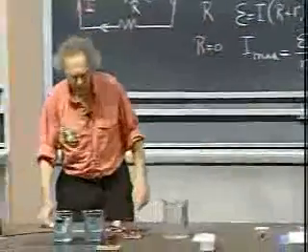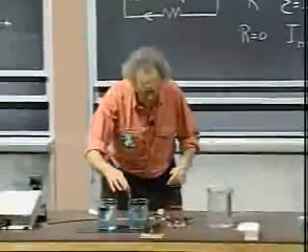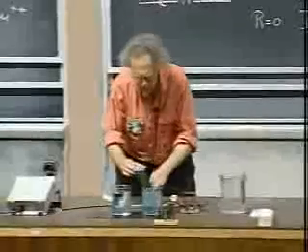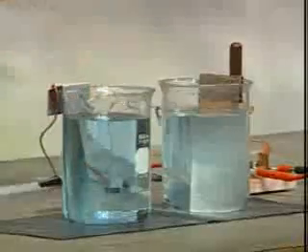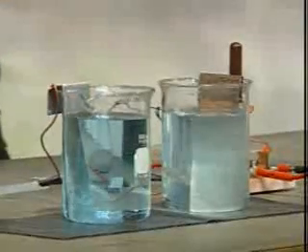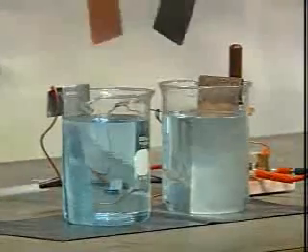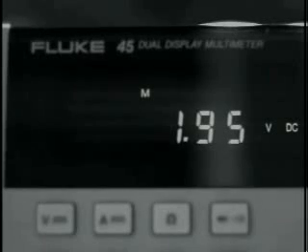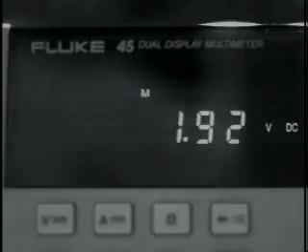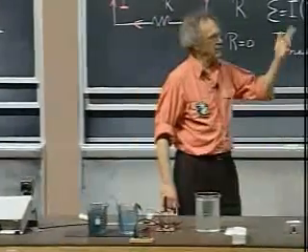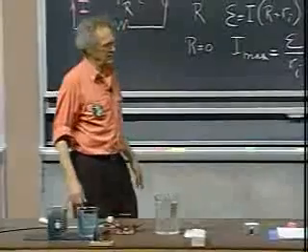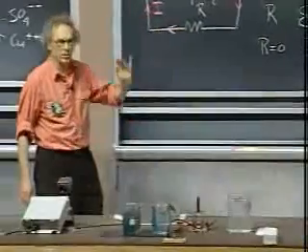So if we're ready for that, this is my second one, is going to be completely independent. So here comes the other 2 plates. Make sure that I have the copper and the zinc not confused. There we go. And now you should see twice the potential, and you do see that. It's open circuit, there is no current running. Well, there is a minute little small current running through the voltmeter that you see, but that's so small that that can always be ignored. And you see you get double the EMF.